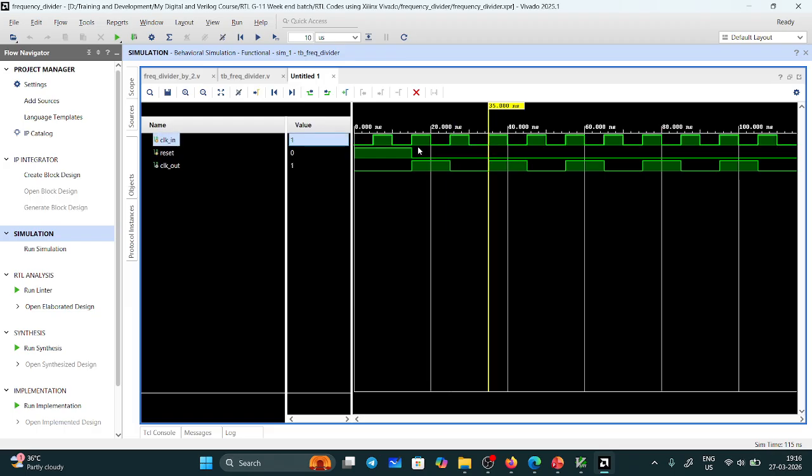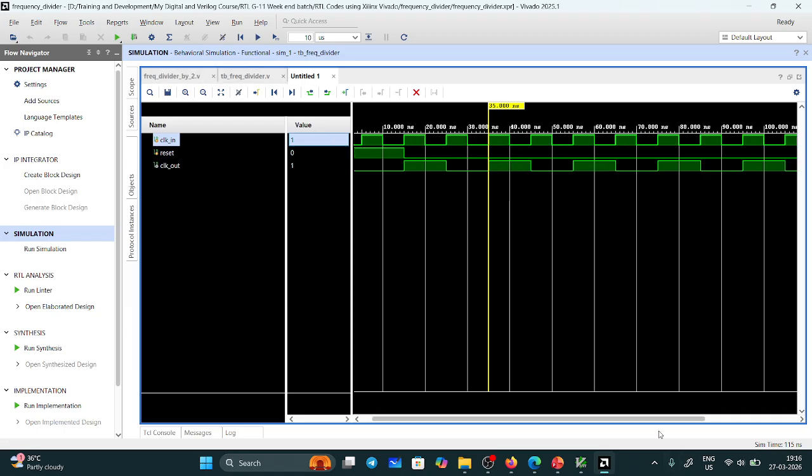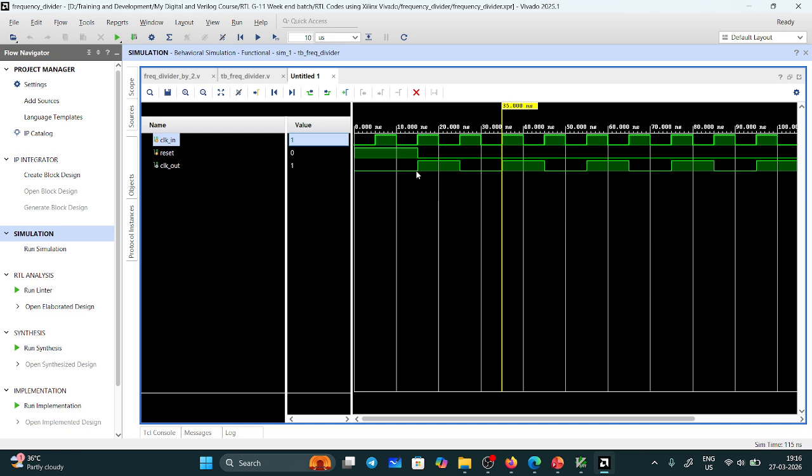Okay, so that means time period. So here, this one time period equal to what? You are getting two time periods. So that means time is doubling, frequency is divided by 2. Okay, so just you can zoom this, you can see over here. So from 10 cycles and here 10 cycles, total 20 cycles. It is taking 2 cycles, but here it is taking 1 cycle only. So as the time period is double, frequency will be half. Frequency is divided by 2.